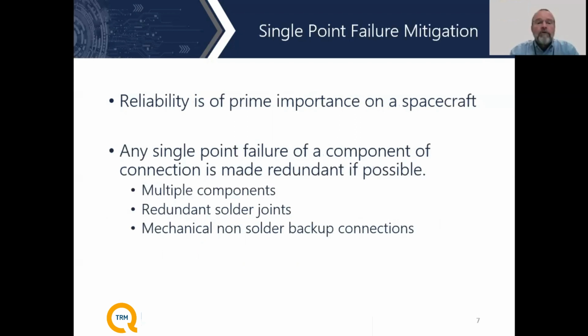Sure. So single point failure mitigation is something that all of our customers always speak to us about. The single most common failure on almost any product is the interconnections or the solder joints. So in order to bring the mean time between failure, or MTBF, numbers much better, our customers ask us to have multiple redundant connections.